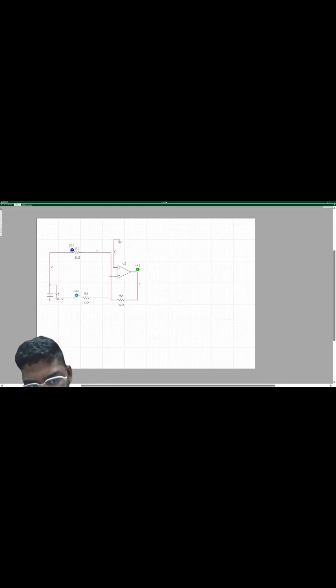Okay, the next part is the conclusion of this circuit. Now we are going to conclude. The simulation confirms that a BJT operates efficiently as a switch for controlling an LED. When sufficient base current is applied by the push button, the transistor enters saturation and enables current to flow through the LED, lighting it up.